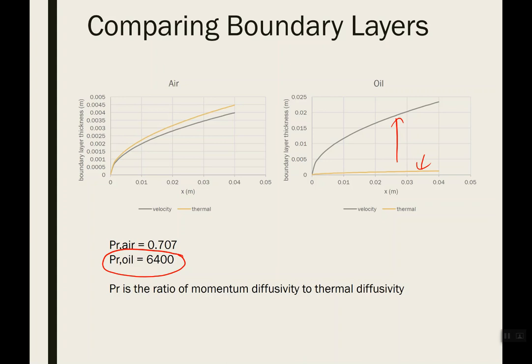There's going to be a transition. So the thermal boundary layer describes what happens right near the surface of the table. And similarly, the thermal boundary layer thickness is when the temperature gets 99% of the way to the bulk fluid temperature. So really there are some microscopic things happening with convection.